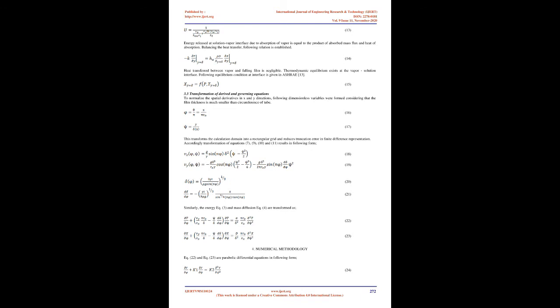1. Resolving the forces acting on the fluid element for a horizontal tube at an angle from the vertical axis yields Equation 2. Neglecting pressure gradients, viscous dissipation, heat conduction in the direction of flow and transport of energy by mass diffusion, the energy analysis of the elemental volume reduces the energy equation to Equation 3.